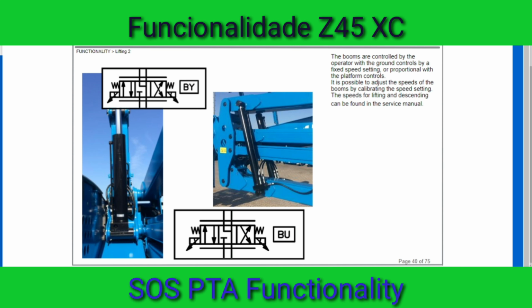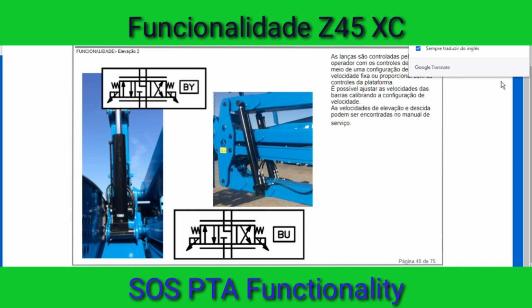The booms are controlled by the operator with the ground controls by a fixed speed setting or proportional with the platform controls. It is possible to adjust the speeds of the booms by calibrating the speed settings. The speed for lifting and descending can be found in the service manual.